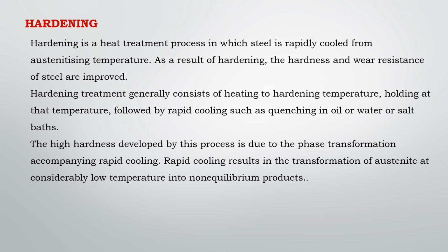The high hardness developed by this process is due to the phase transformation accompanying rapid cooling. Rapid cooling results in the transformation of austenite at considerably low temperature into non-equilibrium products.